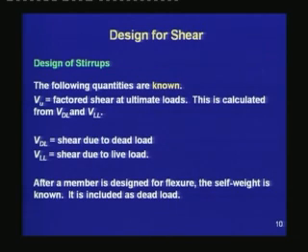For the design of stirrups, the following quantities are known. First, Vu, which is the factored shear at ultimate loads. This is calculated from VDL and VLL. VDL is the shear due to dead load and VLL is the shear due to live load.